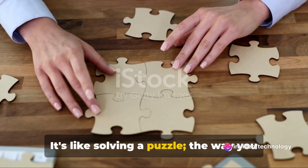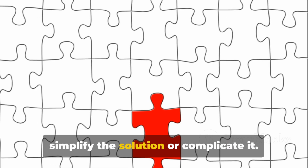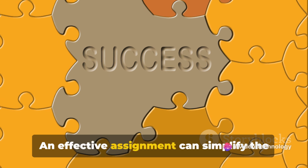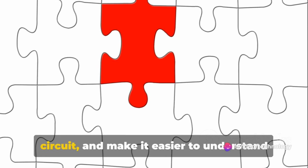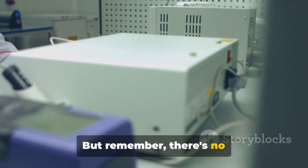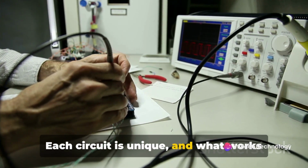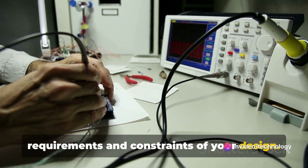It's like solving a puzzle. The way you arrange and connect the pieces can either simplify the solution or complicate it. So careful thought needs to be put into state assignment. An effective assignment can simplify the logic, reduce the complexity of the circuit, and make it easier to understand and troubleshoot. But remember, there's no one-size-fits-all approach to state minimization and assignment. Each circuit is unique, and what works best will depend on the specific requirements and constraints of your design.